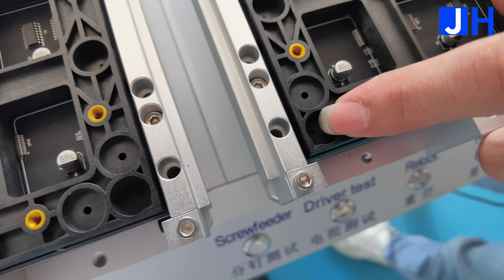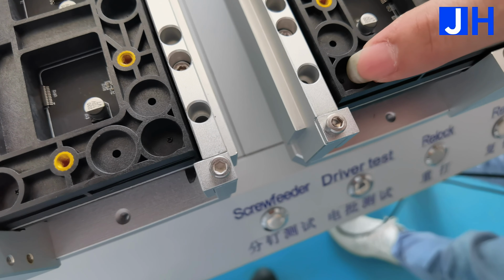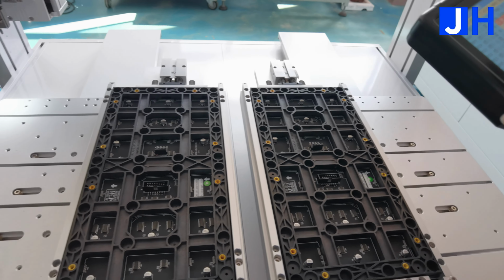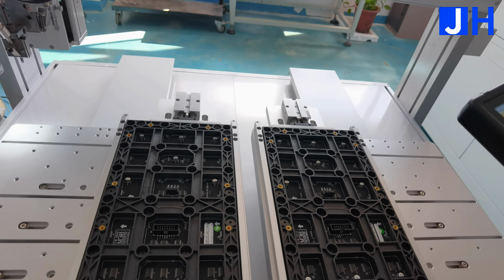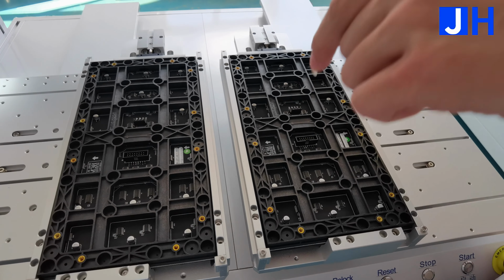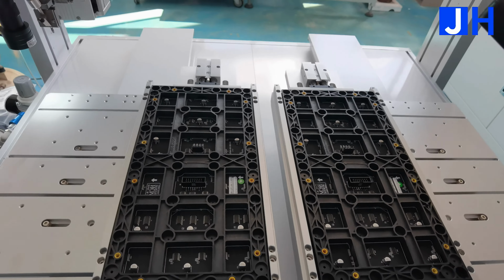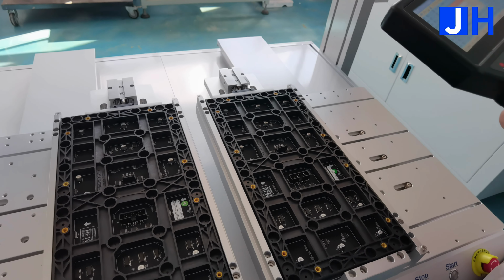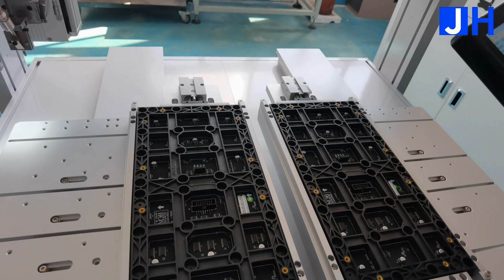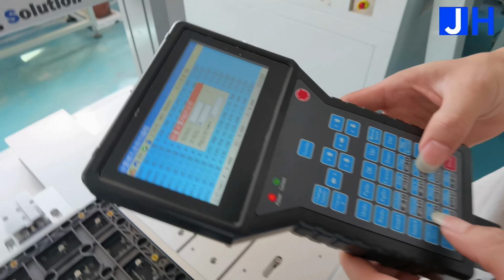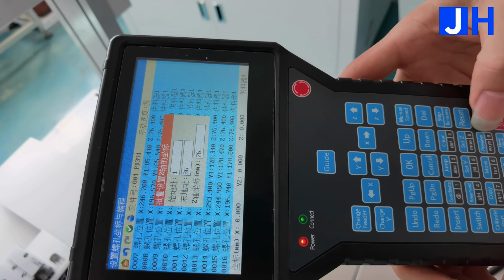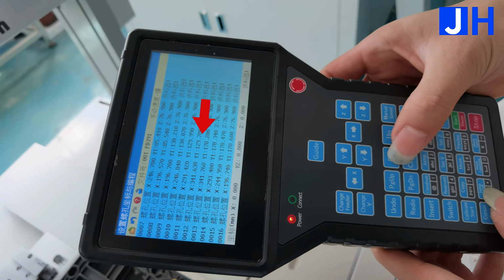As the screw hole coordinates were not centered on the red cursor, the screw failed to engage with the hole during descent. We need to align with the coordinate center of the screw hole, then set the Z-axis descent depth. We are increasing the depth along the Z-axis. Z-axis descent depth increased from 76.4 mm to 76.9 mm.